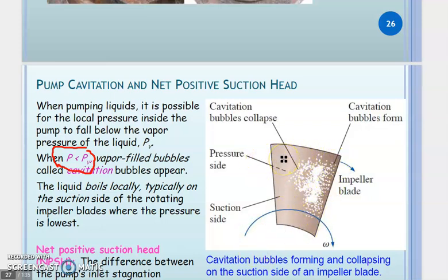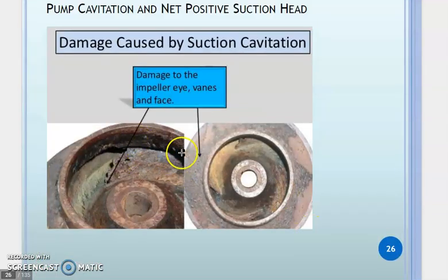When the pump rotates at very high rotation, the bubble will explode. Even though that explosion is tiny, a micro explosion, for example, it is actually repetitive and occurs at the same location. So this will produce cavitation. I mean, this one will later become damaged. Okay, it needs to be repaired. So a hole forms here. So this is the example.